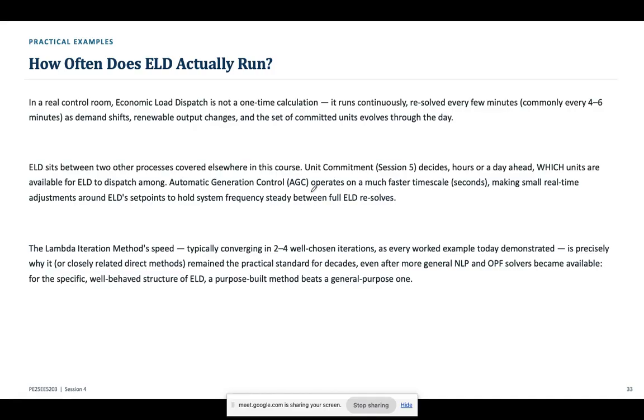Renewable generation provides a useful modern example. Solar and wind have a very low short-run marginal cost because there is no conventional fuel expenditure for each additional megawatt generated. When available and technically deliverable, they can therefore appear at the low-cost end of a merit order representation. However, low marginal cost does not guarantee unlimited dispatch. Transmission congestion, system security, balancing requirements, and curtailment can restrict the output as well.